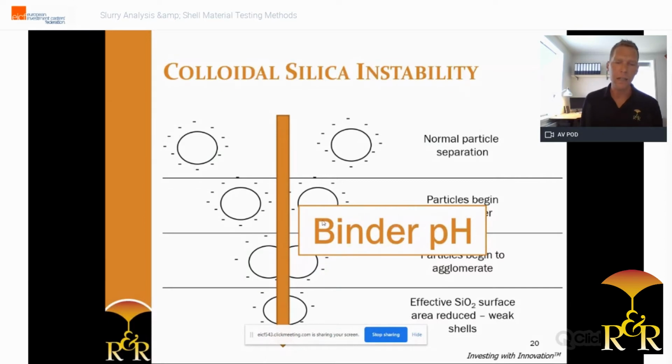So I think it's highly recommendable to invest once in the required equipment and the work area to perform slurry analysis, because this will prevent major issues with slurry and shell quality. And slurry analysis must be encouraged with good quality materials, training, and give people the time to do this, because it will pay back.